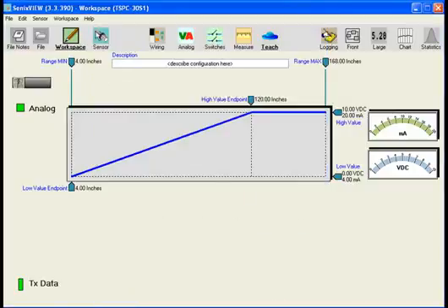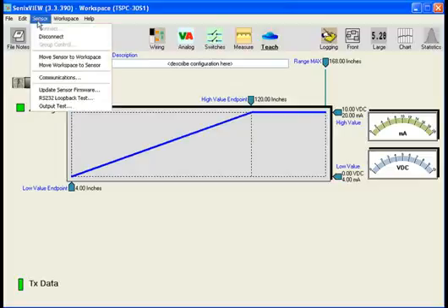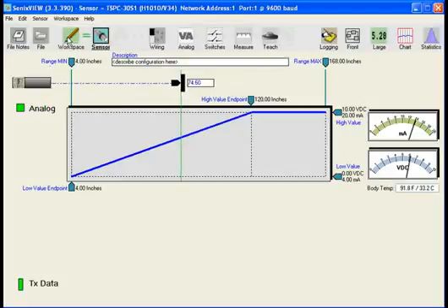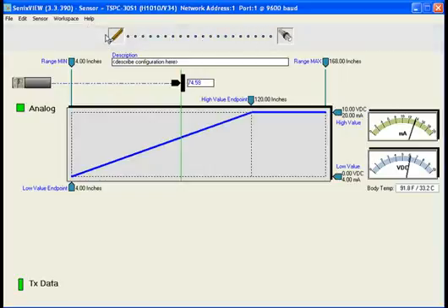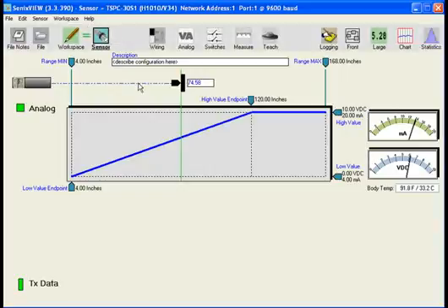And now you'll notice that we have a not equal sign between the workspace and the sensor. What we have to do is download to the firmware the changes we've made in the workspace. Two ways to do that. Sensor menu, come down to Move Workspace to Sensor. And you notice the pencil will write to the right. Alternately, you can right-click on the workspace icon, see the other pencil come up, and we can just drag it to the sensor and release it. It achieves the same thing.